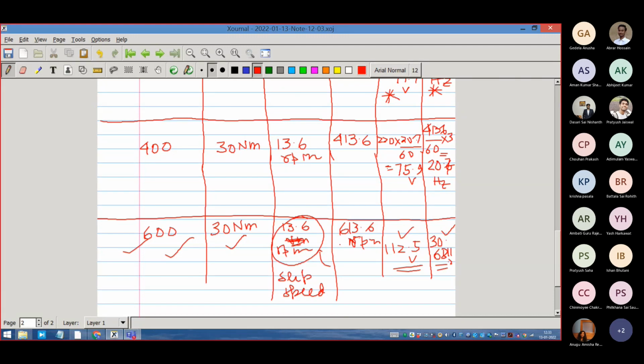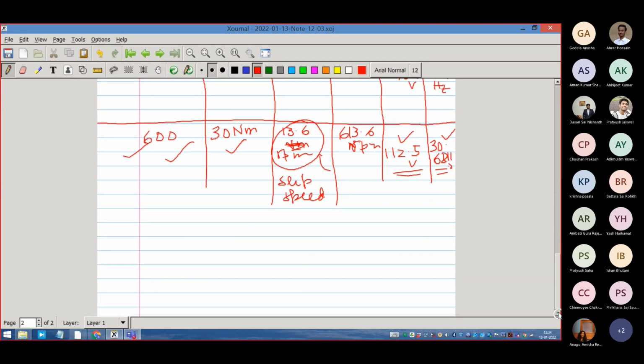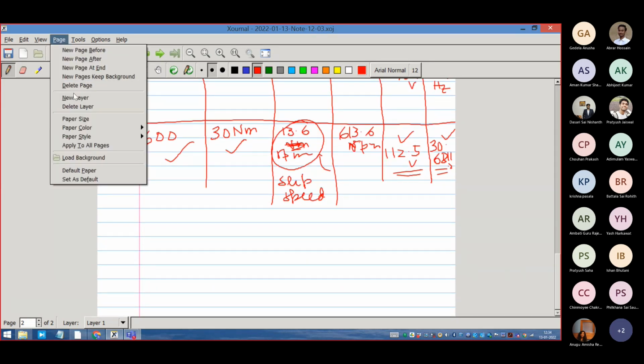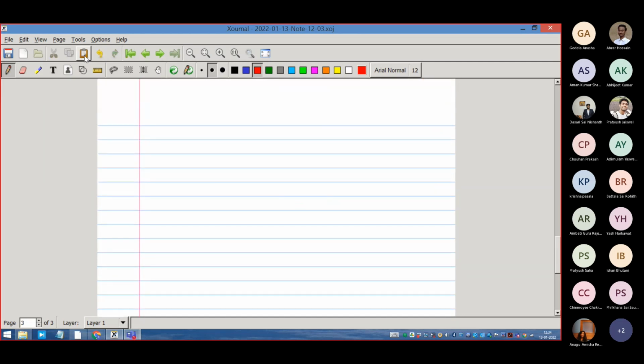And for that particular time, whatever may be the parameter of the machine, taking consideration of the temperature, saturation, etc., all other things, it will develop the precise amount of slip speed that will ultimately develop the torque, as well as control or regulate the speed at the reference value, the rotor speed at the reference value. So let me draw the control system now. Right. So let me draw the control system of this scheme.